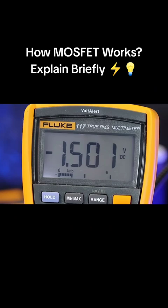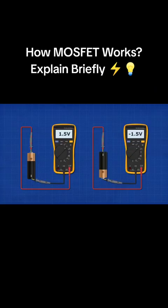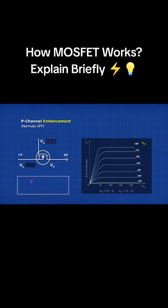Negative voltage sounds confusing, but even a battery can be a negative voltage. It just depends where we take reference from. In this case, if we had 9 volts on the gate but 0 volts on the source, then we have a positive 9 volts, so the MOSFET is off. If we had 9 volts on the gate and 9 volts on the source, we would have 0 volts of difference.